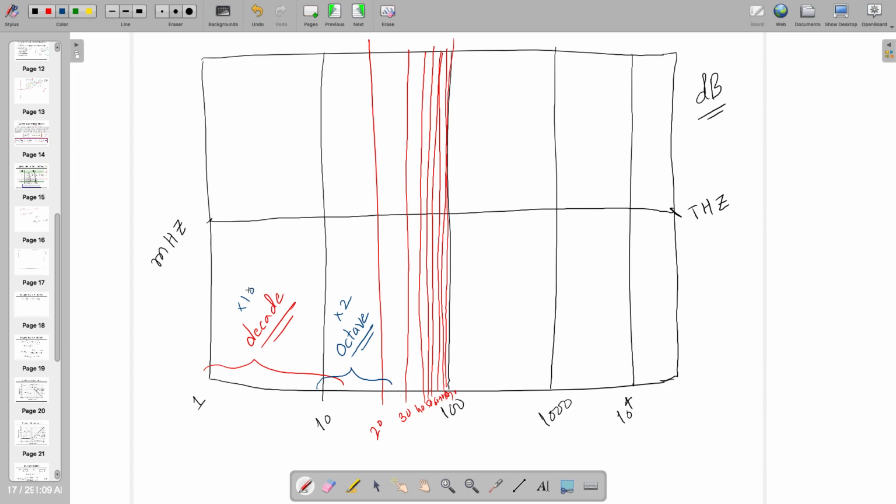Just to find out some slope, because Bode plot is dealing with slope. Till now we have not learned it, but slope is measured in decibel per decade or decibel per octave. This is the standard practice people are following. So we are going to use this one. All the electronics engineers follow dB per decade, meaning analog circuit designers, digital, all these.